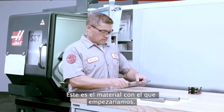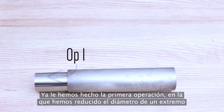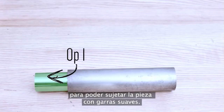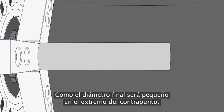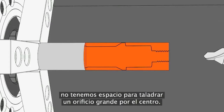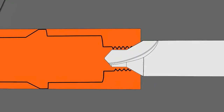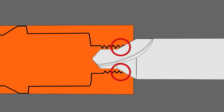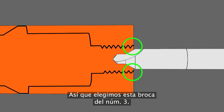Here's the material we'll be starting with. We already completed Op 1, where we turned the bar stock down so we can grip it with our soft jaws. Because our finished diameter will eventually get small at the tailstock end, we don't really have room for a large center drilled hole. So we'll choose this small number 3 center drill.